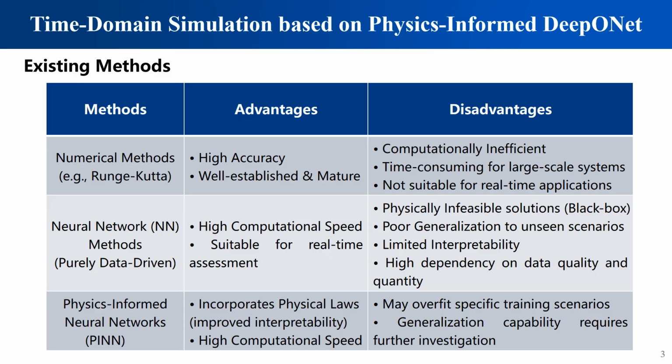This is also a practical modeling choice. In a grid study, the fault location, clearing time, generator loading, and network parameters can change from case to case. Repeating a full numerical simulation for every case is costly. A pure neural model may be fast, but may lose the meaning of power balance. The physics-informed operator tries to preserve both sides: rapid inference and equations that still express rotor dynamics.